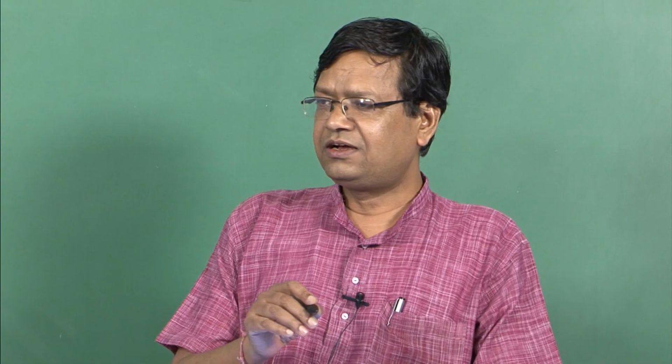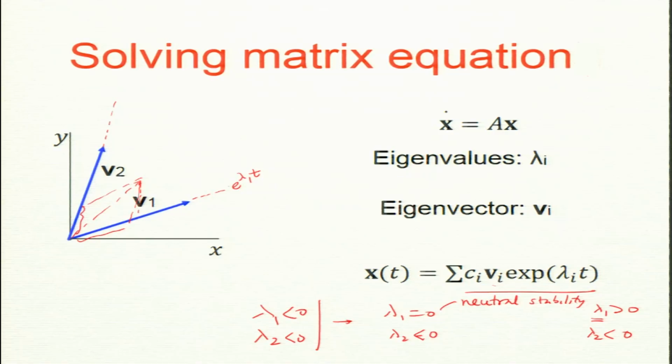So, in the previous discussion we had the equation of the form x dot equal to Ax. Now, this is a linear equation, so it has eigenvalues and eigenvectors. For our case the equation was 2D, in u2 and theta. So, it has 2 eigenvalues and 2 or fewer eigenvectors, but I will show you that there are 2 eigenvectors. Now, the eigenvalues will tell us whether the system will grow or not, I mean the velocity field will grow or not. And how does the eigenvalue tell you?